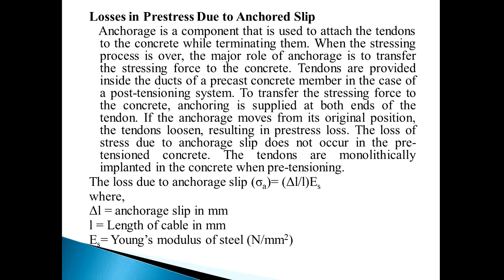So anchorage is a component that is used to attach the tendons to the concrete while terminating them. When the stressing process is over, the major role of the anchorage is to transfer the stressing force to the concrete. The tendons are provided in the ducts of the precast concrete member in the case of the post-tensioning system. To transfer the stressing force to the concrete, anchorage is supplied at both ends of the tendons. If the anchorage moves from the original position, the tendon loosens, resulting in pre-stress loss.